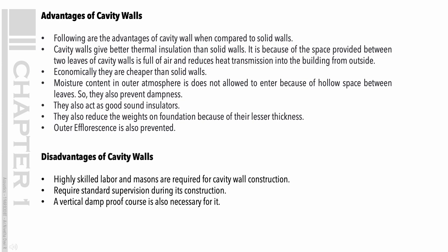They also act as good sound insulators. They also reduce the weight on foundation because of their lesser thickness. Efflorescence is also prevented. Disadvantages of cavity walls. Highly skilled labor and masons are required for cavity wall construction. They require standard supervision during construction. A vertical damp-proof course is also necessary for it.